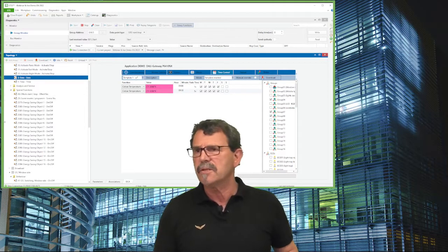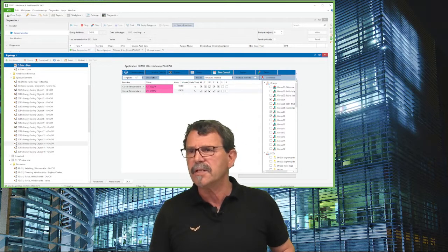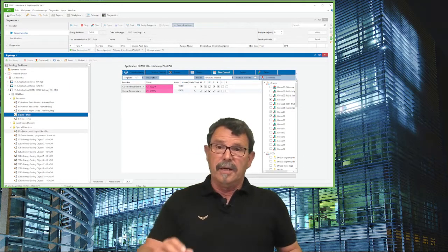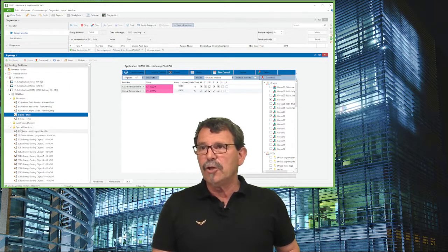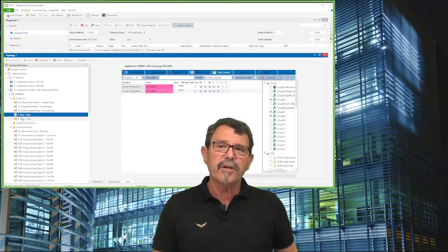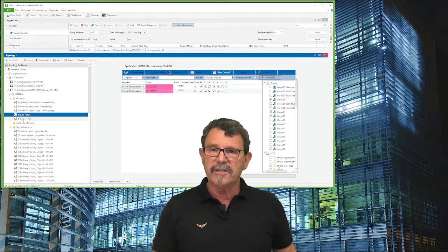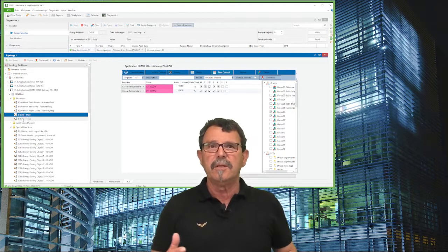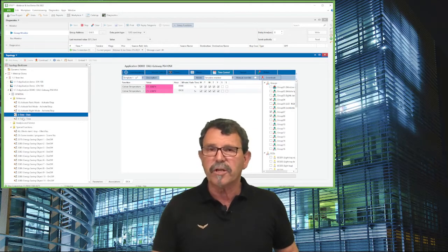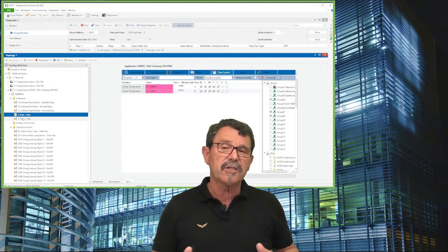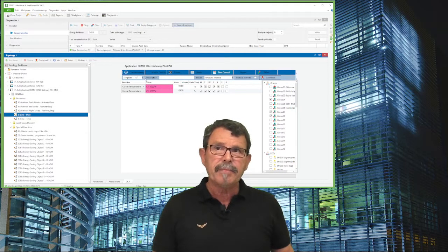2095. This is somewhere hidden in this huge amount of communication objects, and here you just have to give an on command, so you can activate or deactivate this, and then exactly at that time this procedure starts, and you can stop it individually. You can start and stop by a time switch, you can do it manually, whatever you like. Okay, this is how it works finally.